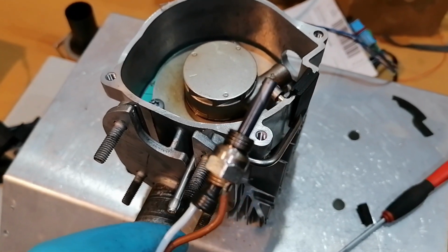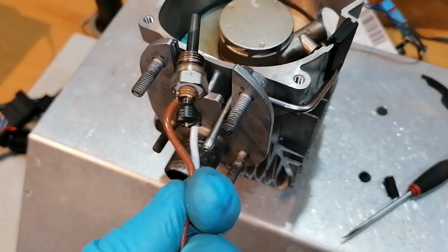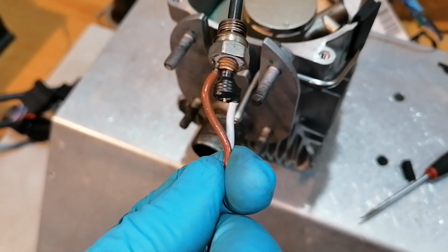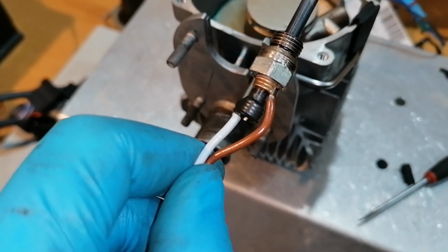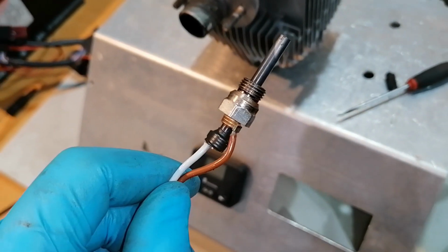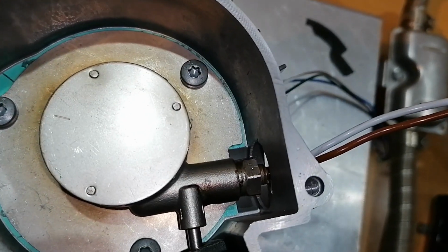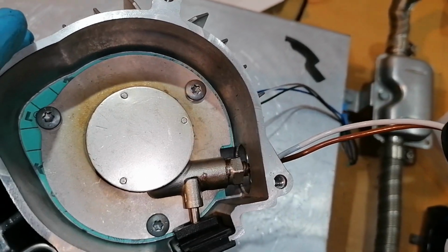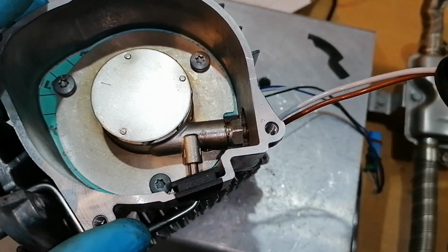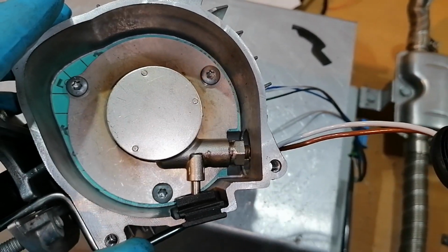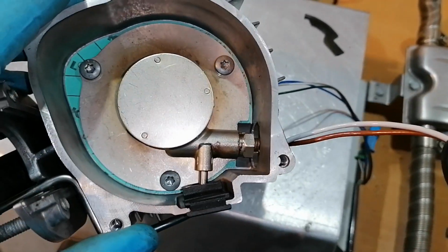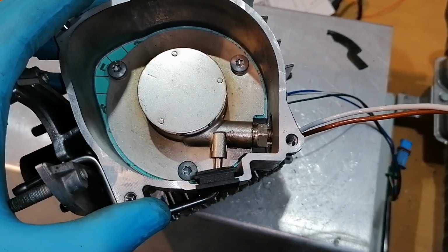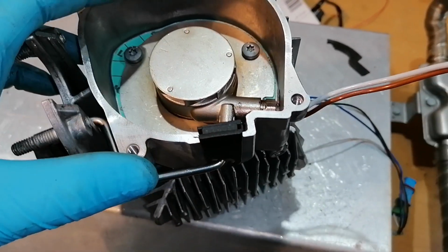It's time for the glow plug. I just cleaned it a little bit, but be very careful with these wires because they can easily snap off, and then there's nothing really else you can do but buy a new one. Okay, so now that's in. Just be careful, do not over tighten it. It should be tight, but it's not really a bolt that needs to be tightened very hard. Or else maybe next time you take it apart, it will be very hard to take it out.